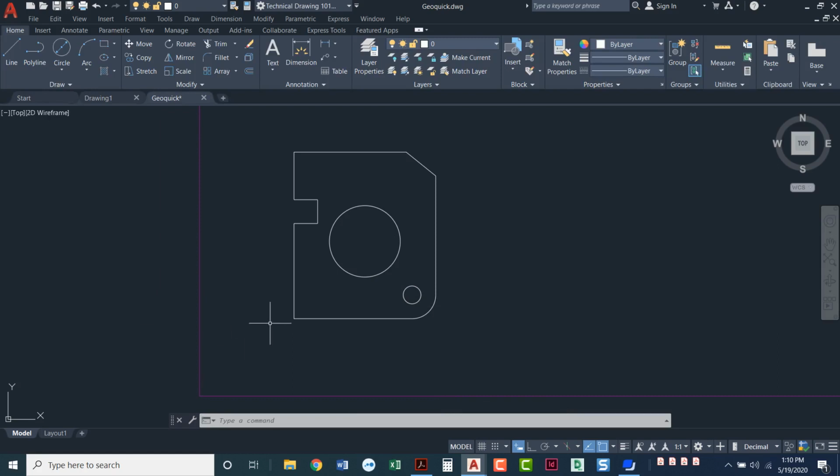We're about to draw another circle, and it is the exact same situation. You could draw the circle command first using the from O-snap, or you could do the fillet first, and you could just draw the circle based on that fillet. I'm going to do it with the fillet first. I think that's a much easier way to do this. So I'll say fillet.